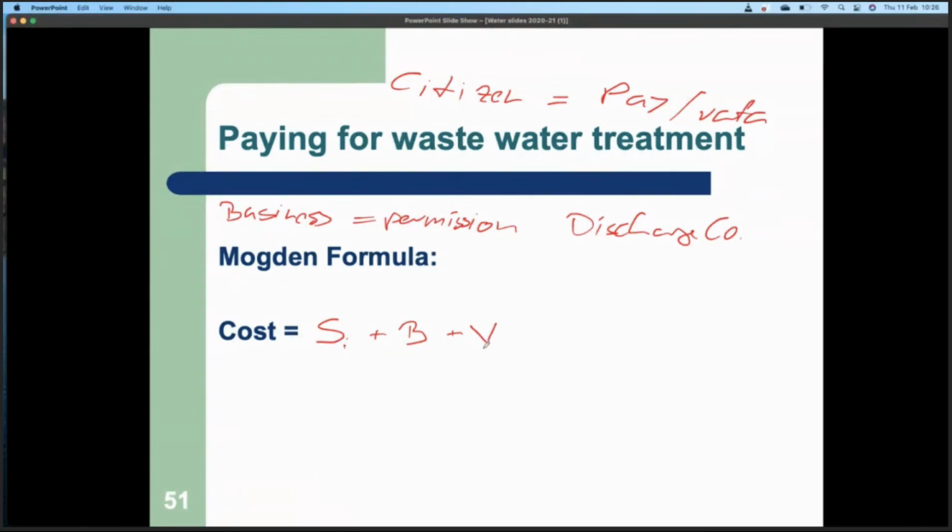And then the sewage works has to deal with all this volume of water, the size of the tanks and the treatment pumps and all this sort of stuff. But also there's some efficiency considerations, because if you dilute stuff into very high volumes of water, then it gets very hard to treat it. So in a way, there's a tendency to say you concentrate your wastewater as much as possible, because it makes it easier to treat. The efficiency of treatment is better if it's less diluted. So they charge you for volume, and they charge you for something else.